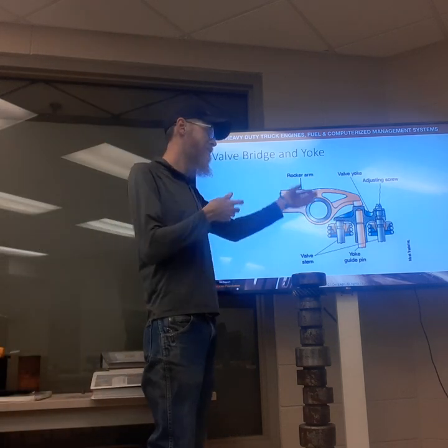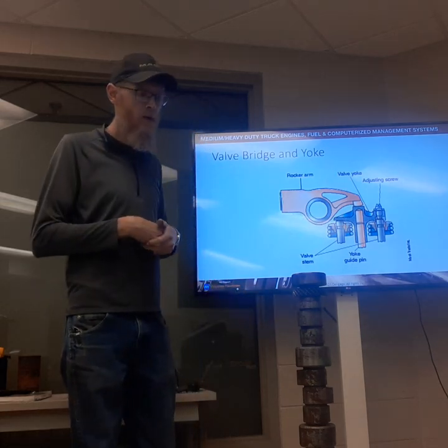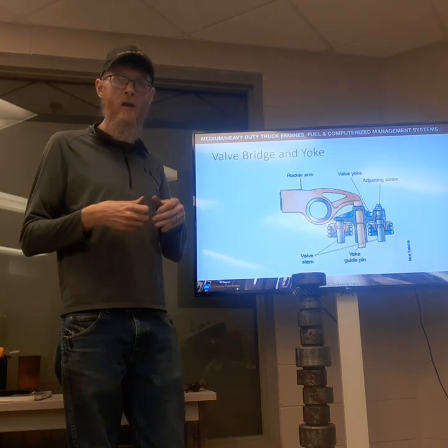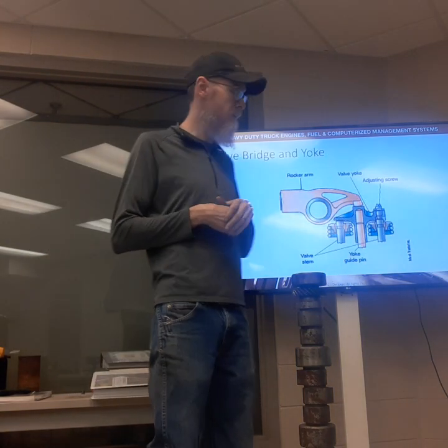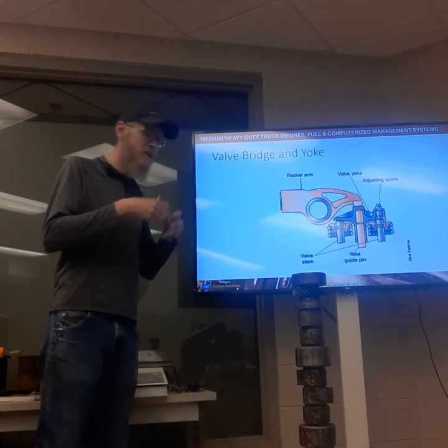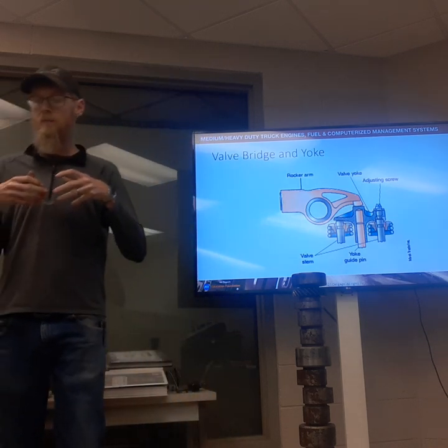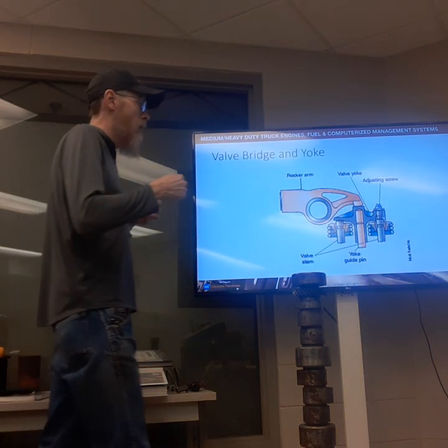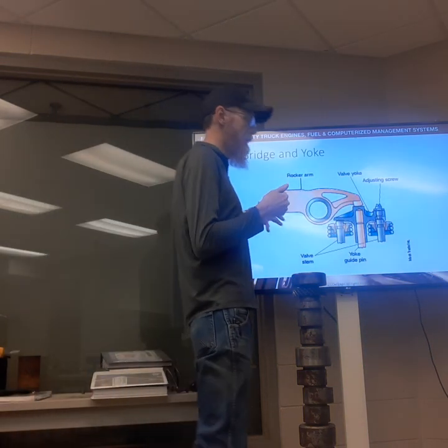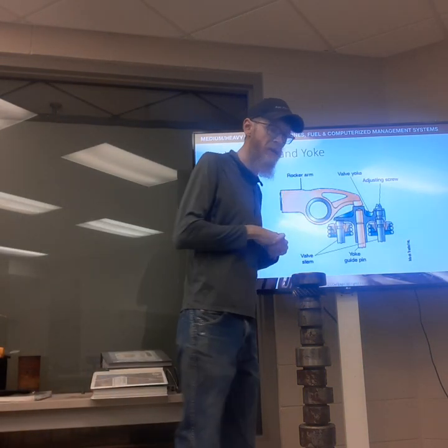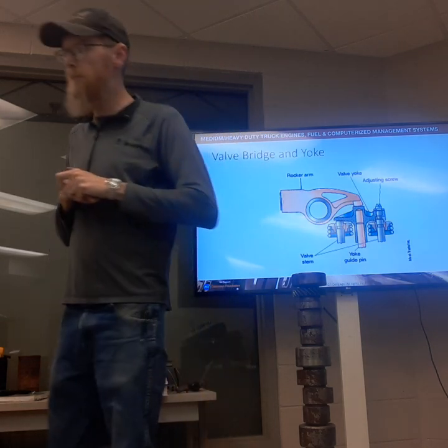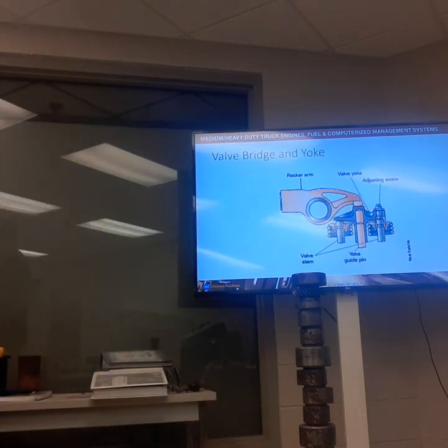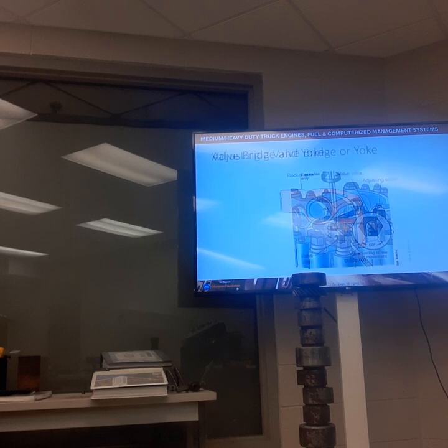This is very similar geometry to how we actuate the plungers on the fuel injectors. All the same procedures are required when adjusting our rocker arms in relation to our fuel injectors.